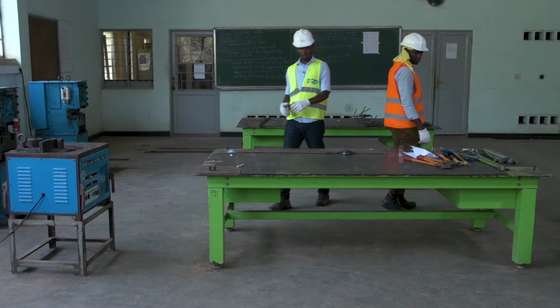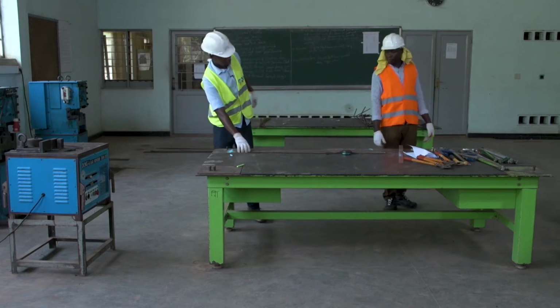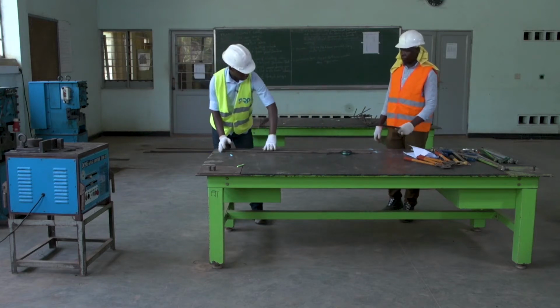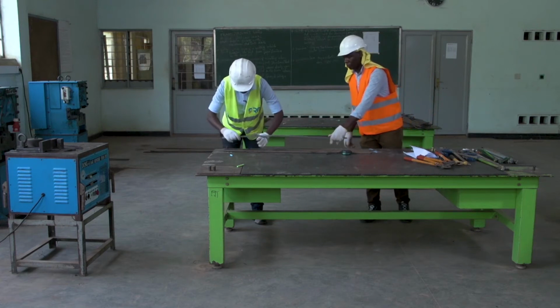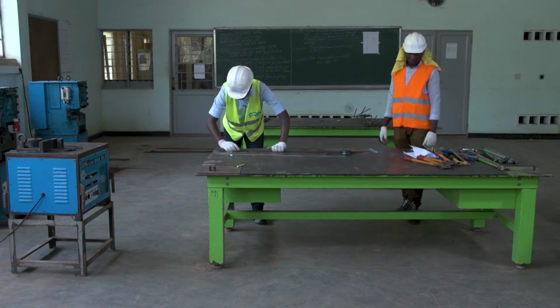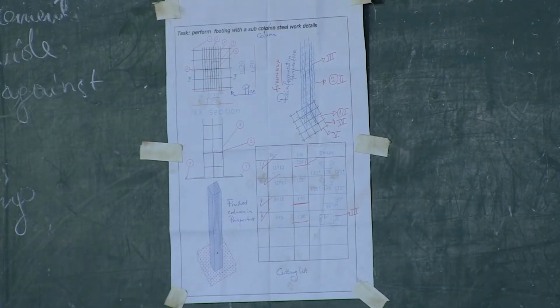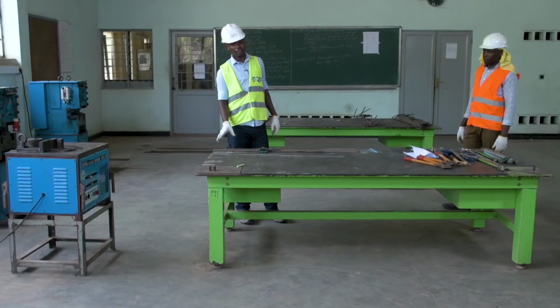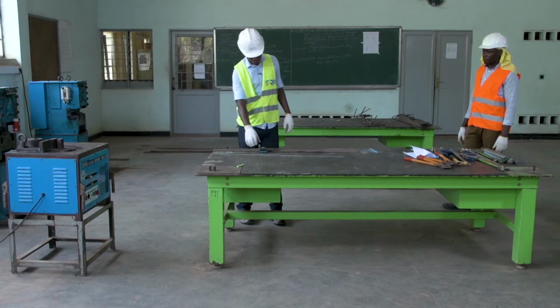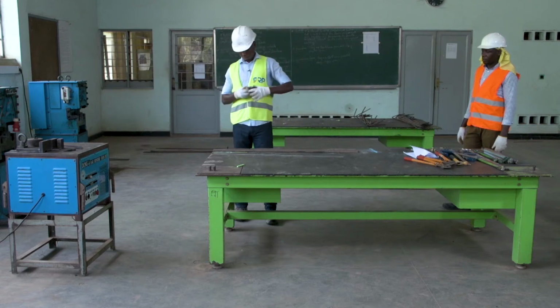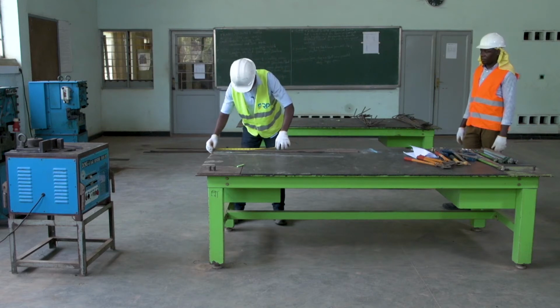Next step, we are going to mark the steel bars for a subcolumn. The steps are the same as the footing. Remember, the bending part of subcolumn is 30. And remember, the subcolumns will bend one side on angles of 90 degrees. Then let's start to mark 30 centimeters.